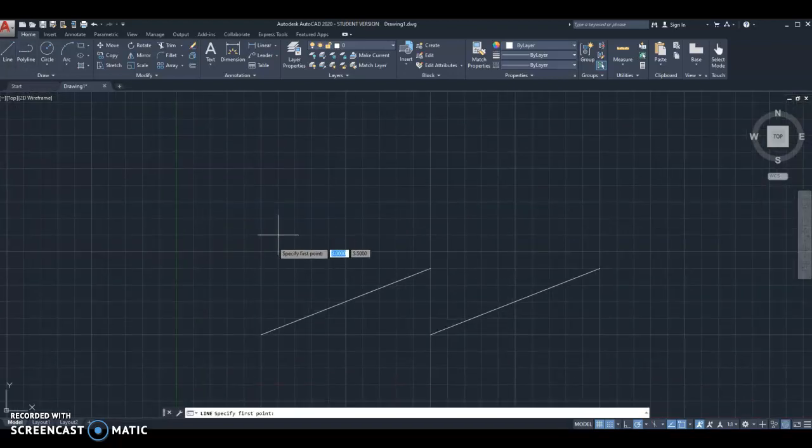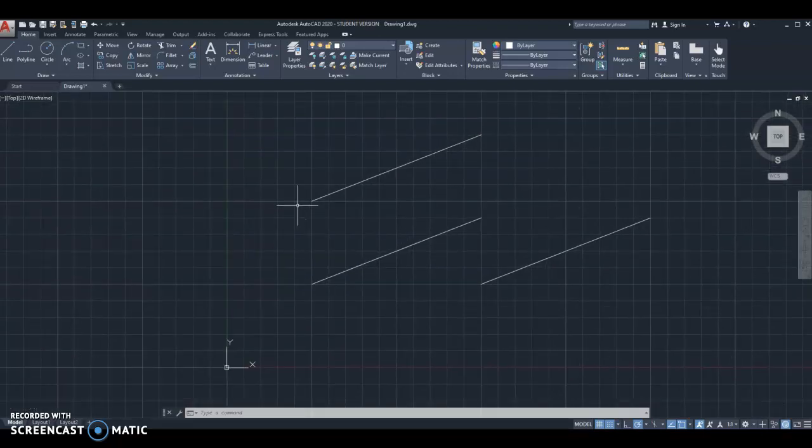And so when the dynamic input is turned on, it is assuming that anytime you key in coordinates, you are meaning to specify relative coordinates, meaning that having chosen a point right here, if I want to choose a second point for my line and I key in 5, 2, it assumes that I want the next point on my line to be 5 inches over and 2 inches up relative to my starting point. The alternate to relative coordinates is absolute coordinates, and they always start off at the origin.